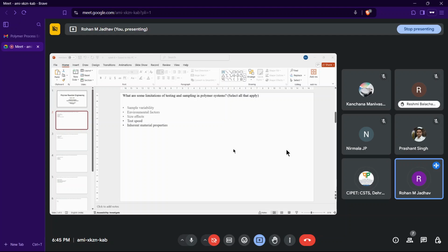Oxidation can also come, but that comes after the product has been made and is provided an environment where oxygen is there. After some time, UV effects and oxidation take place, and some discoloration comes. But that is a long-term effect, delamination aside. Flash, warpage, sink marks can be immediate or short-term effects, appearing within or after some time.